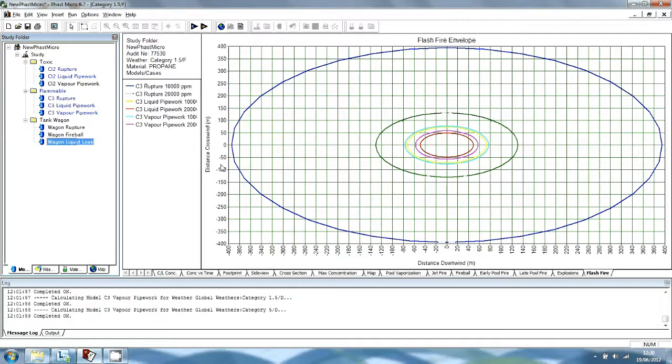For a release from the body of a vessel rather than from attached pipework, you should set the scenario type to leak. This will give a larger discharge rate since there are no frictional losses during the flow to the leak location. For the leak scenario, you specify the leak size in the Scenario tab section. The leak is assumed to be at the top of the tank, which is the most conservative assumption from the tank head and the duration.